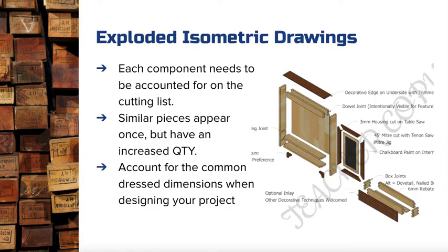I would always start with an exploded isometric drawing. I get my project, I draw it in SketchUp, each piece is an individual component, and then I put it here in exploded view, pull each piece apart slightly, and then I can count all of the individual pieces on the screen. The benefit of doing it like this is it means that I don't miss anything. I can see each individual component, and it also proves that I've got all of my components created in SketchUp, and that's an extra skill for me when it comes to the drawing aspect of the project.